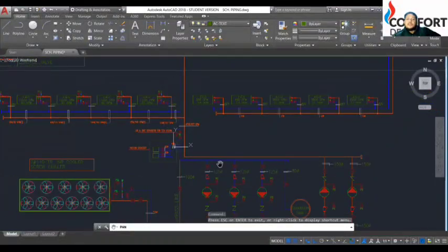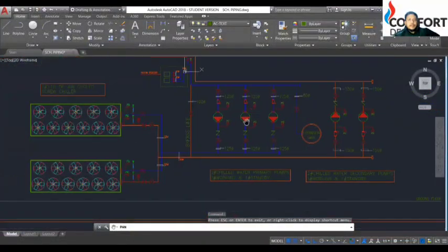यहाँ पे आपने 3 पंप्स are used, and these are your primary pumps which connect your AHU और FCU to chiller. जो AHU FCU को चिलर से कनेक्ट करता है. पंप के सक्शन में हमेशा वाई स्ट्रेनर लगता है. There will be a Y strainer at the pump suction.